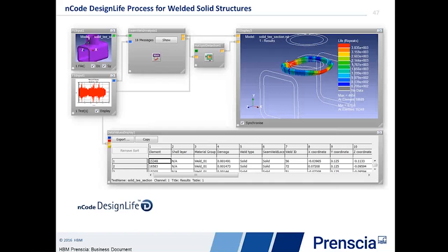In fact, both approaches, the stress linearization, the through thickness integration, and the nodal force moment approach, give us very, very similar structural stresses. So we're using the same weld curves for steel and for aluminum.